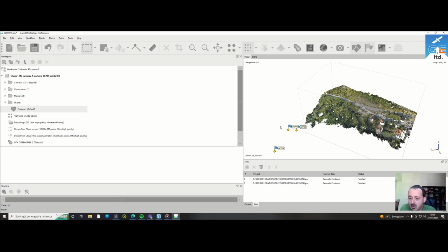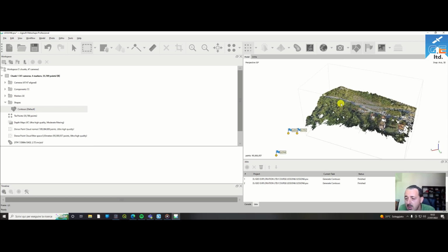Generally the ground control points should be set at the corners of the area, one here, one here, one here, one here, and as we explained well in lesson 2, we need to make a grid of ground control points, one here, one here, one here, one here. This calibrates the elevation model and prevents distortion of the area.